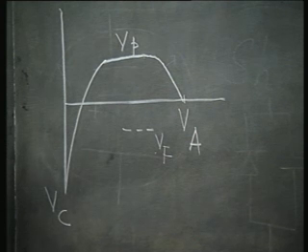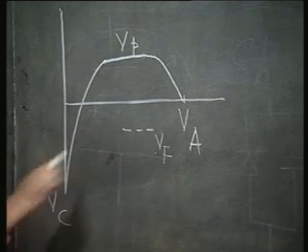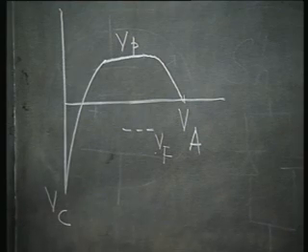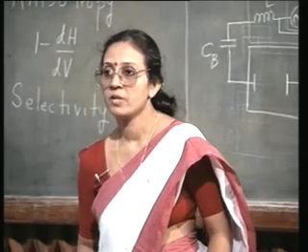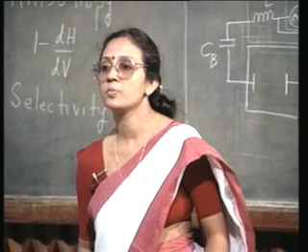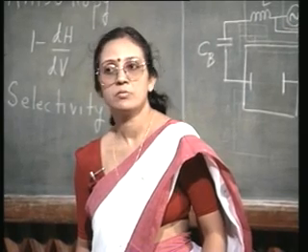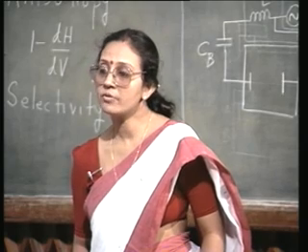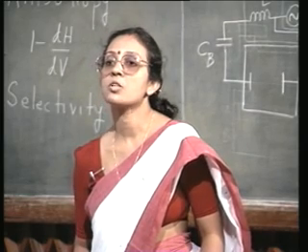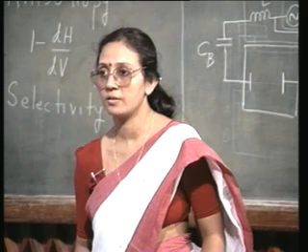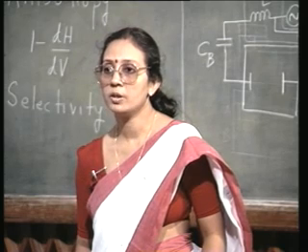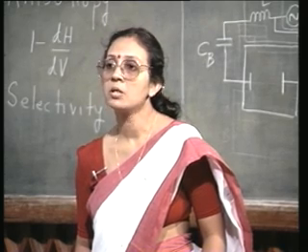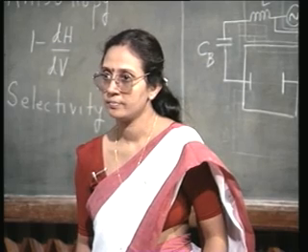But even then, Vf is a small negative value. So, Vp minus Vf is not going to be significantly different from Vp minus Va. So, even if you place your substrates on an insulating surface, the ion bombardment energy is going to be relatively less.